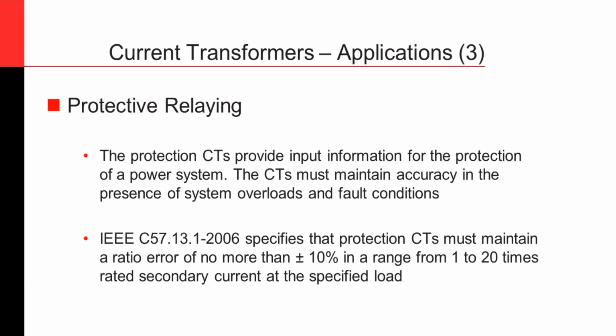One of the other major applications of the CT is protective relaying. As I told you before, I would consider the CTs and PTs like the eyes of a power system, where it constantly monitors the current flowing through the primary and also the voltage on the line. So since you measure the voltage and current on each and every single line in each and every single node, you're pretty much calculating the power, the P, Q, S, power factor, pretty much everything associated with the power system.